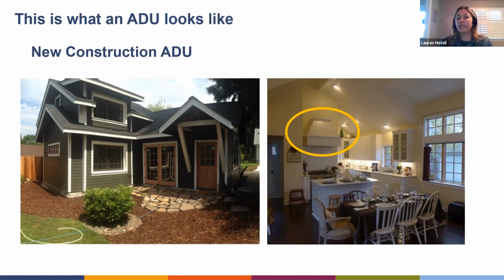The exhaust is required under the energy code to provide a way to get the air out of the kitchen. And you can also use some type of inline fan, but we called out the range hood because it's a very nice example of one. And a fan can be useful when you're kind of space constrained, but you also have to have some way to exhaust the air. So that's why we point out this exhaust hood.